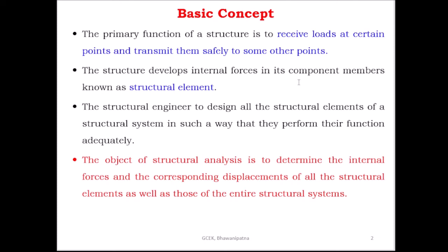They form a system consisting of a load resisting component, which is called superstructure, and a load distribution component to the ground, which is known as substructure. All the structures are designed in such a manner that they sustain the loads coming on them during their service life by possessing adequate strength and also minimize the deformation by possessing enough stiffness. The strength of a structure depends on the characteristics of the material used during the construction, and the stiffness depends on the cross section and the geometrical configuration of the structure.